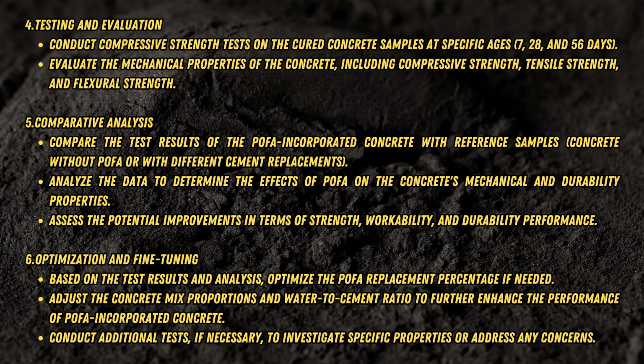After that, we need testing and evaluation. Conduct compressive strength tests on the cured concrete samples at specific ages, which are 7, 28, and 56 days. Evaluate the mechanical properties of the concrete, including compressive strength, tensile strength, and flexural strength.